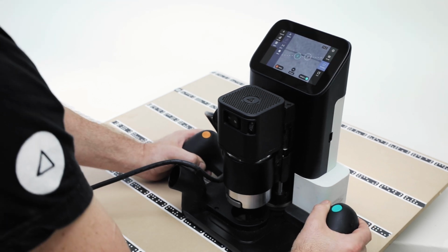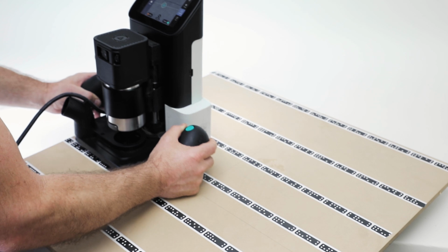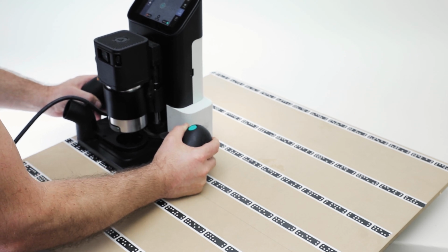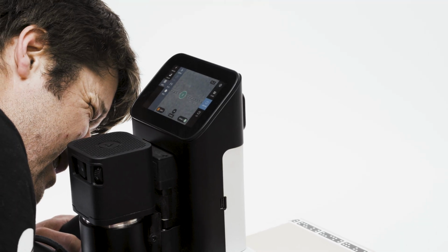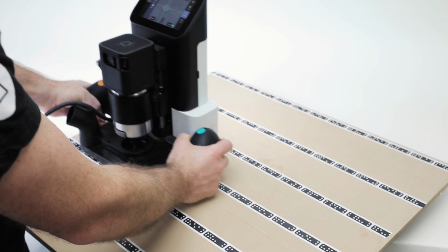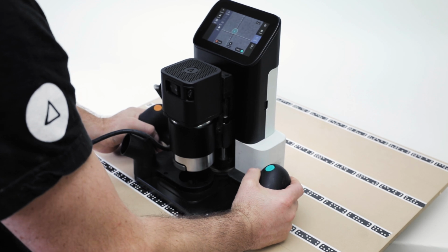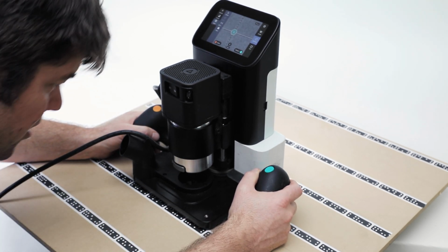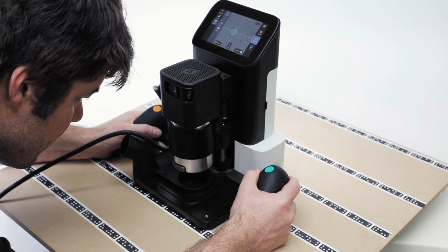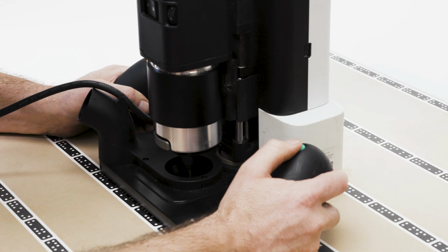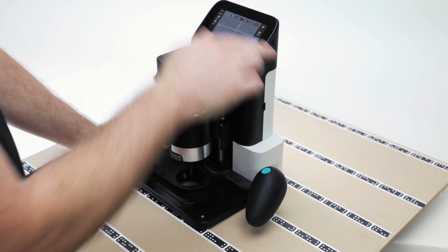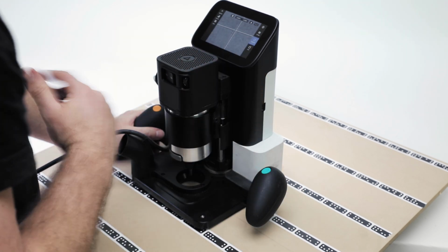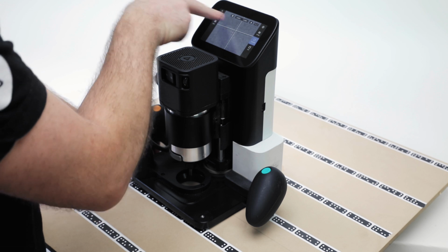So now as I drag, I can quickly see on the screen that I'm vaguely correct. But I'm going to confirm I'm where I want to be by looking down at that cutter hovering above my pencil mark. Once I'm happy with that, I move back to the center, and I can see it's automatically switched to the center mode for my y-axis as well. Once I'm happy with that, visually looking at the point again, not the screen, hit accept, and we've got a perfectly aligned grid here. So for projects in the middle of a large area, that's really powerful.